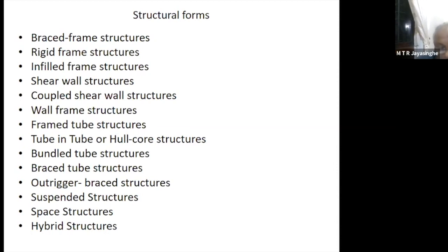The moment you do that, you create the washroom drop within the slab, and if you can control the width of that to 1.5 meters, very good, because the maximum space in between two adjacent strands is 1.5 meters. So if you can confine the washroom drop with careful planning to be less than 1.5 meters, the slab does not know there's a drop.